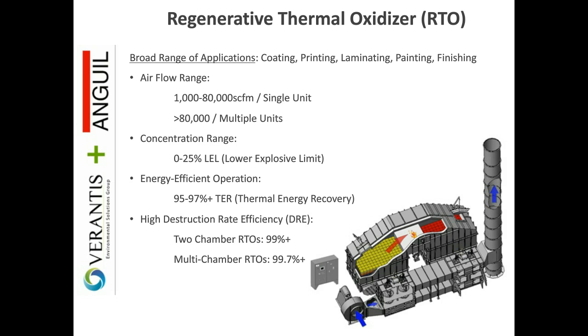The concentration range, 0 to 25% LEL, which is the lower explosive limit of the specific compounds we're dealing with. That also tends to coincide with what the NFPA allows you to treat without additional safeties in place. Energy efficiency, 95 to 97%, and this is really why the RTO is the number one technology right now: we can achieve 95% on the low end and 97% on the high